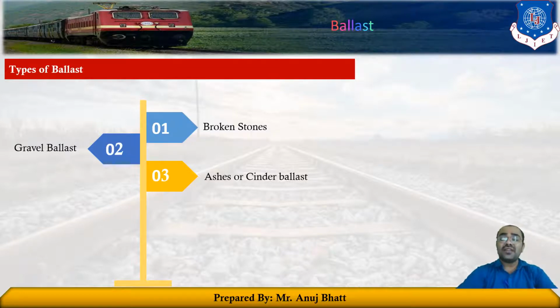Yes, this material has a fairly good drainage property, and it is widely used at the railway yards to keep them dry and non-slippery during the rainy seasons. While the cost of such material is very low, this type of ballast can be made available in a large quantity in a short period of time. This type of ballast is of corrosive quality, and hence it is not used where steel sleepers are provided.